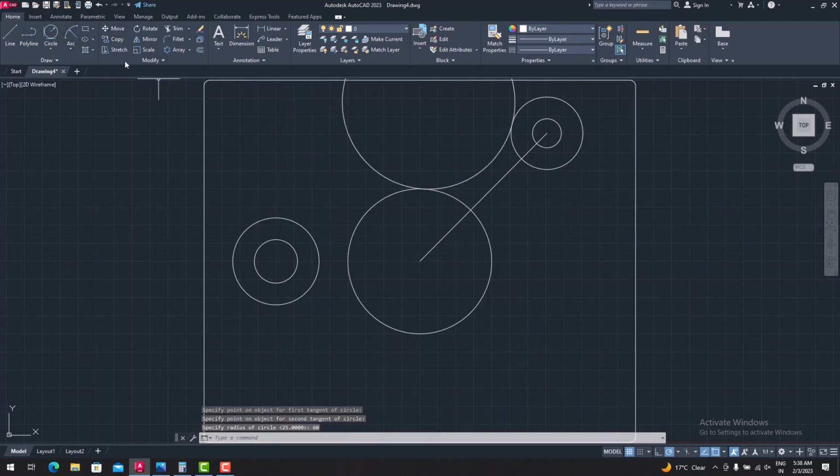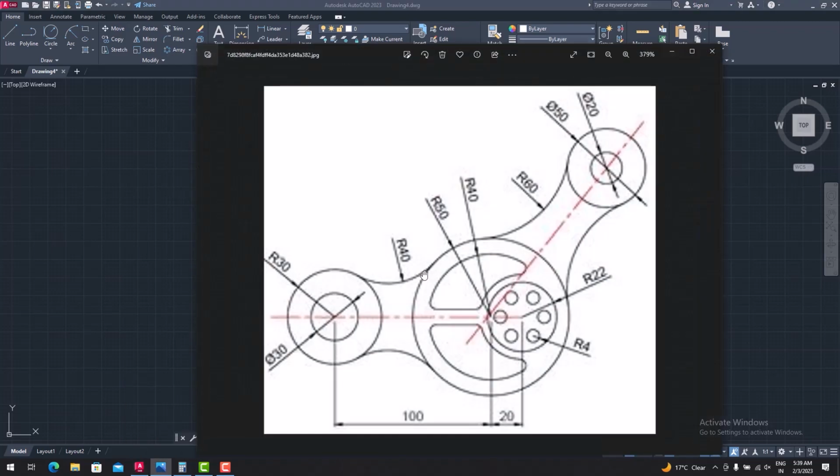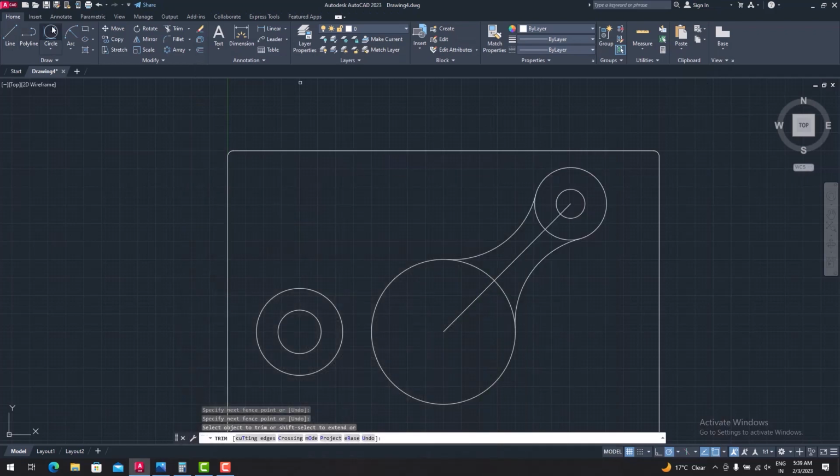Yes, it is in correct form. Okay, so these two sides are created. Now remove this excess material like this. Okay, and again here also you can see there is a curve with a radius 40. So take this circle, tan radius, and specify the radius point.